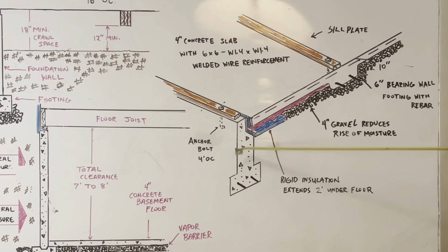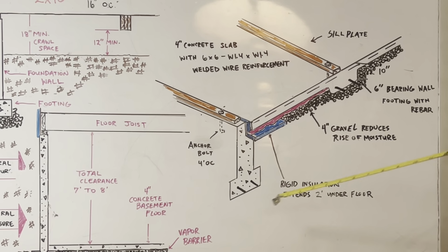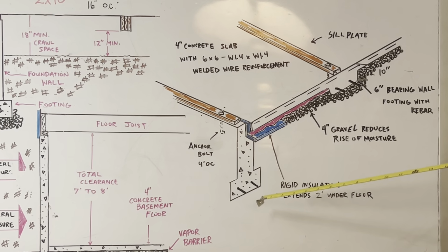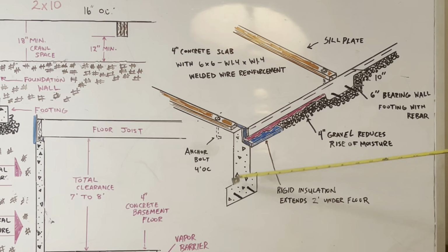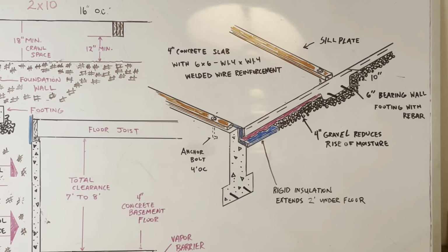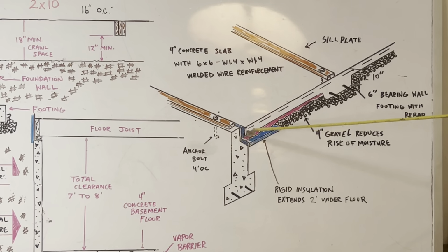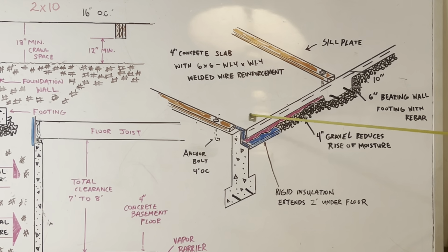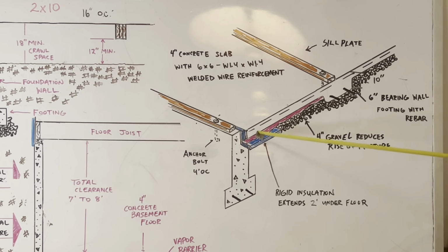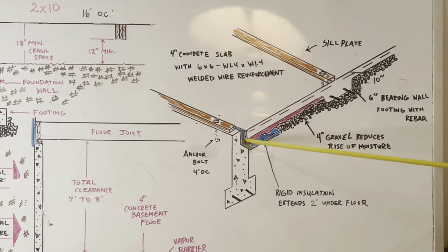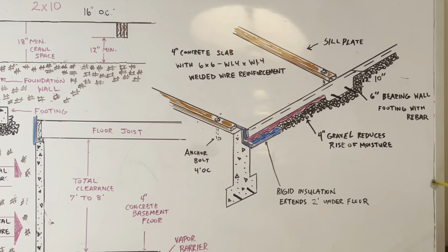We got an inverted T. You see, inverted just means upside down. Okay, so you see how this looks like an upside down T. That's your footing. This is your wall. It has a shoulder right here that I'm not showing. So your slab is gonna sit on at least a 4 inch, has at least 4 inches of bearing, or 4 inches of support upon it. Okay.